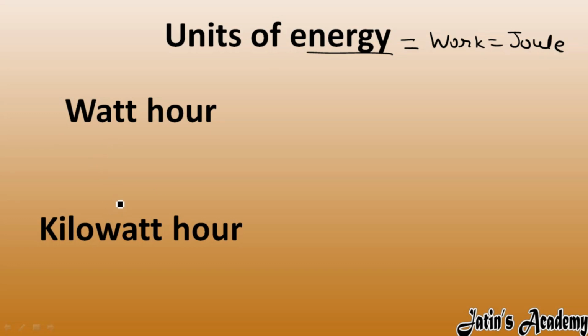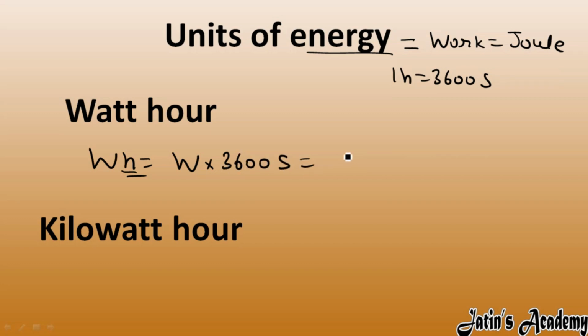Now what is our work? Our work is to convert watt hour into joule. Now how will we do it? Carefully see, watt into hour. So watt remains the same, and for the hour value, in 1 hour how many seconds are there? 3600 seconds. So we have 3600 watt second. Now we have to see the value of watt second.